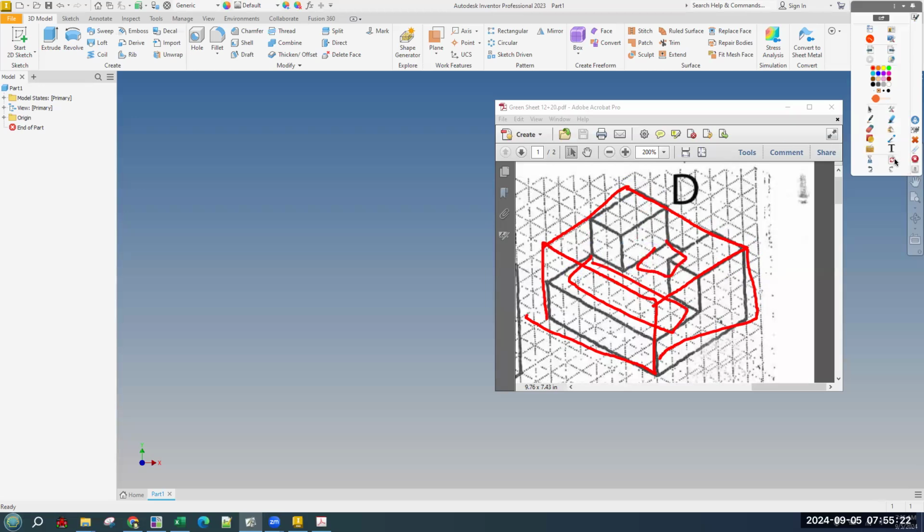I think for this one, it makes more sense to just do this in 2 additive steps, meaning make one block that is this bottom size, which is 2 in the front and 7 wide and 6 deep. So we make a block like this. And then once we have that flat block, make a couple of these size squares and extrude them up. And because these are the same distance extrusion, we can do them in the same move. So we can do the entire thing in 2 moves.